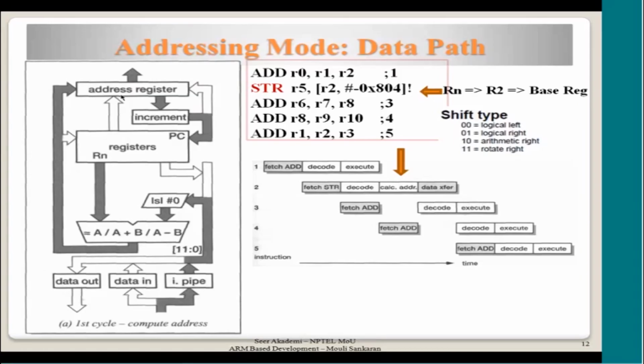What I mean by that is, during the address calculation, this address register is already holding a PC instruction address referring to this instruction number 4. So it is accessing that instruction now, and then once address calculation is done and it is overwritten into this address register, then in the next cycle it will not be doing a fetch. That is why you see that there is no fetch here, there is a gap.